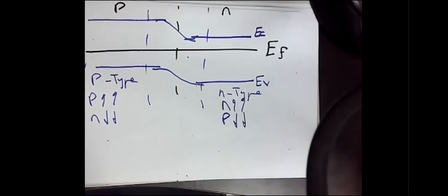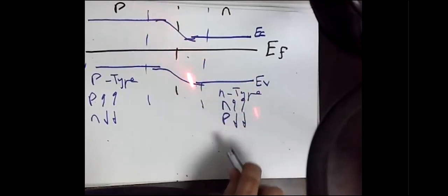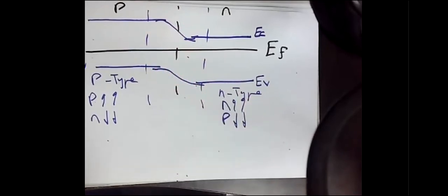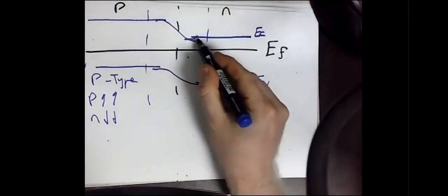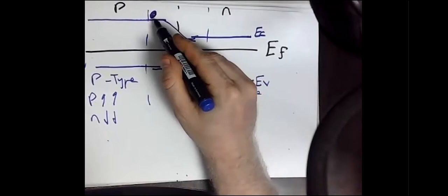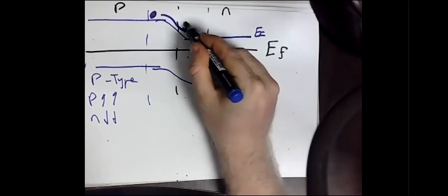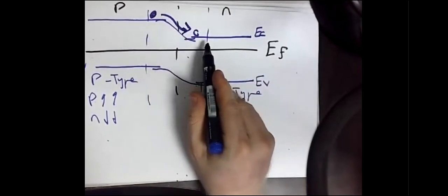So if we examine together this depleted region, the region in between where we have this tilting in the energy band diagram, and I told you, please, my dear student, let's examine what is the direction of the electrical field. I mean, how carriers should move. You will tell me, okay, this is the drift. So if we have an electron here, this electron will tend to have a minimum potential. So it will start to move and go there. So this is the direction of electrons.